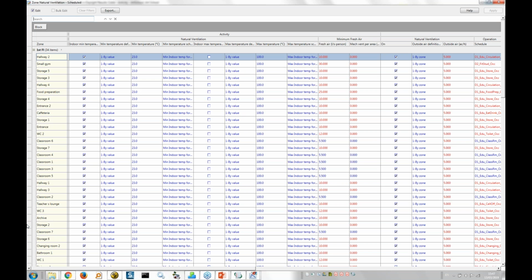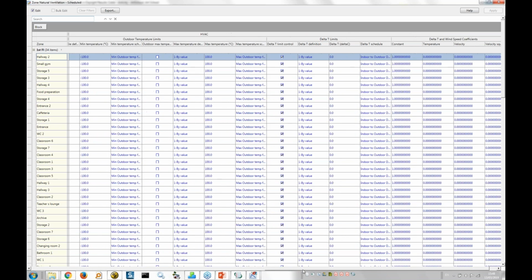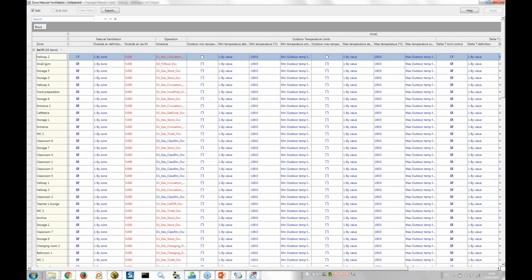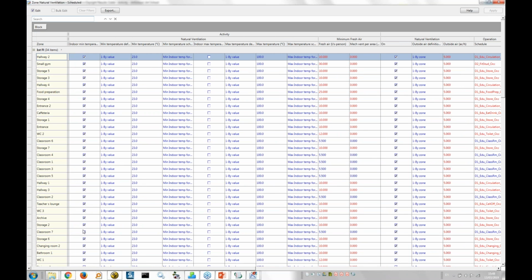What you see in the grid will depend on which analysis mode you're in. So you will see different things, for example, depending on whether you're in EnergyPlus mode, or for those using certification mode such as SBEM or DSM in the UK, you would see something a little different, relevant to the model data for the mode that you're in. Scrolling across the grid, we can review all of the relevant data fields. But we'll now take a quick look and see how we can use the filter tool to edit the data in bulk.